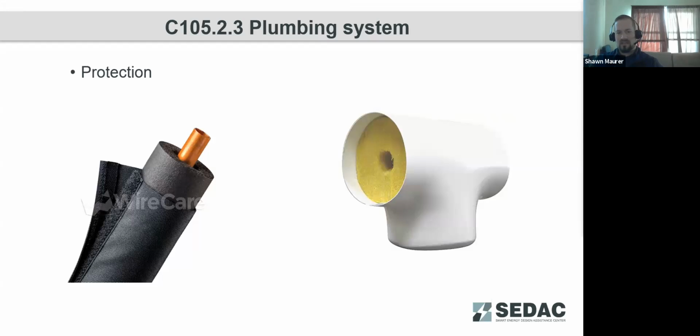So for protection of that insulation piping, one thing to be aware of is that it cannot be an adhesive covering. It must be something that's removable, so that insulation can be removed for maintenance purposes, reinstalled, and then that protective coating put back in place. A lot of these PVC wraps, these all-purpose wraps for inside buildings, can be removed, are generally held in place and closed with some kind of tape sealant that can be cut off, the wrap removed, and then placed back around fittings and joints. So both of these would be in compliance with that code requirement.